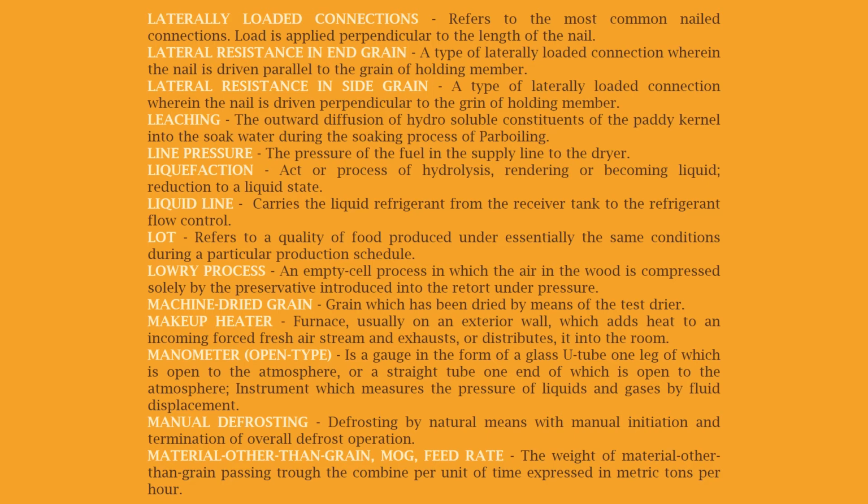Laterally loaded connections refers to the most common nailed connections. Load is applied perpendicular to the length of the nail. Lateral resistance in end grain. A type of laterally loaded connection wherein the nail is driven parallel to the grain of holding member. Lateral resistance inside grain. A type of laterally loaded connection wherein the nail is driven perpendicular to the grain of holding member.